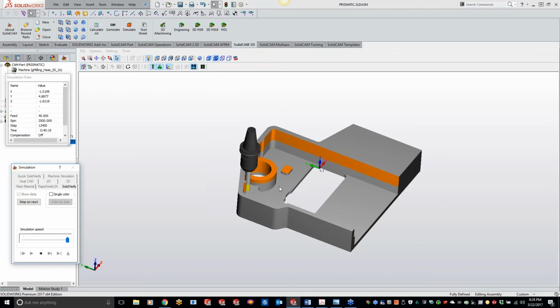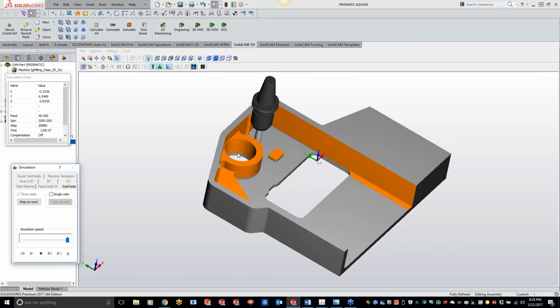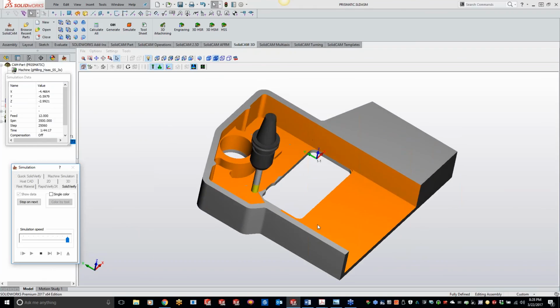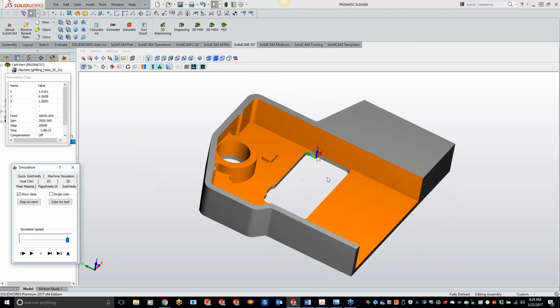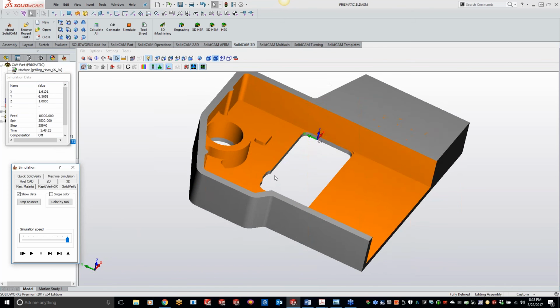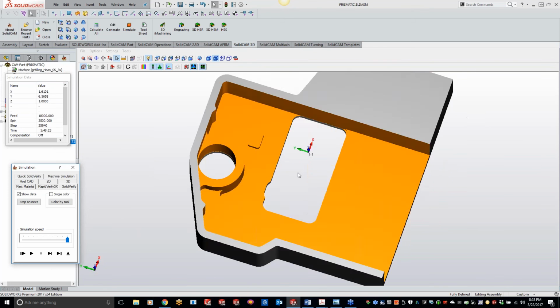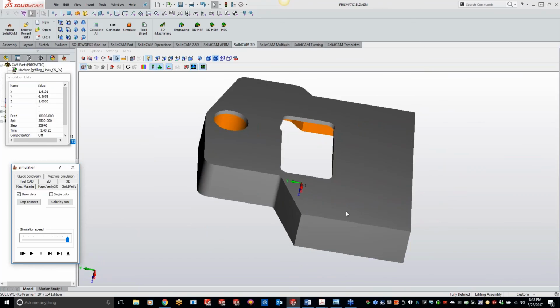And now, since I picked just that bottom surface, that's why you'll see down in that bore we're actually not going down all the way anymore. And we're not actually finishing this. So what I would be doing now is flipping my part over, pocketing out this area, and then finishing this area right here. Or what we can do is pick the bottom of the part, and then I wouldn't have to come back and finish these areas.